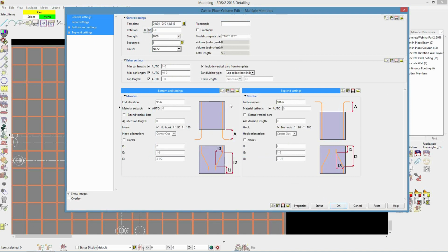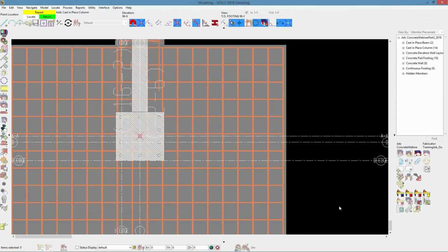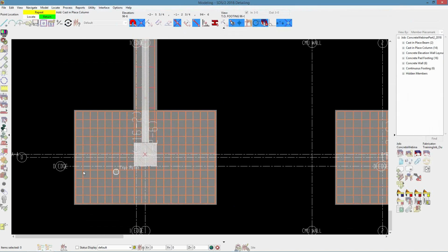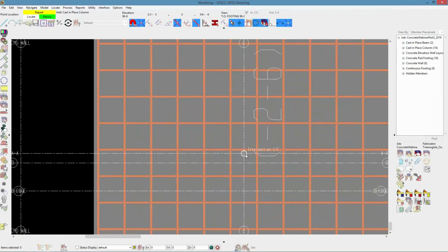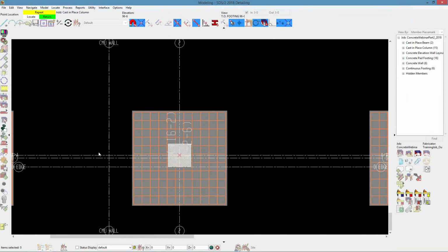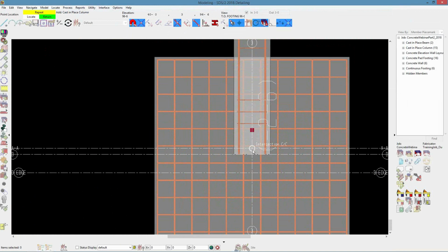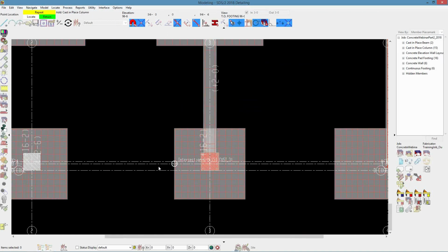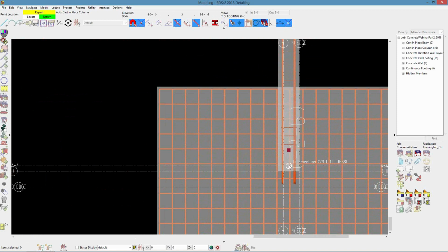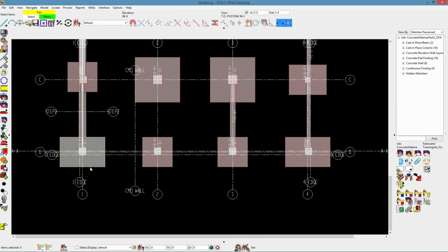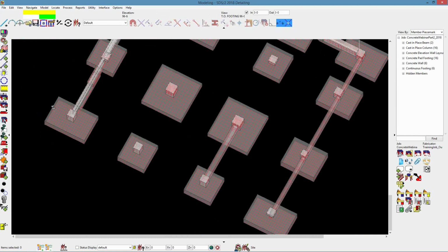I'll go ahead and set my height first. So my end elevation is 96'6" that I placed in here. My second floor starts out at 112'8". So I'm going to go up to my second floor here. I'll go ahead and hit OK. And I will just copy it down the line. Okay, so now if we go back to our original column here,